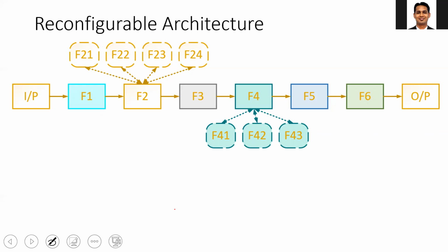Also, it may happen that after you deliver the product to the customer, the customer may say, okay, now I want to upgrade with one more algorithm, say for the night time. So what you need to do is just share the additional files, and instead of 2 algorithms, your hardware can now support a third algorithm. This is called upgradability, and this is where FPGAs are getting more and more popular. What is FPGA? That is the field programmable gate array, while what is ASIC?